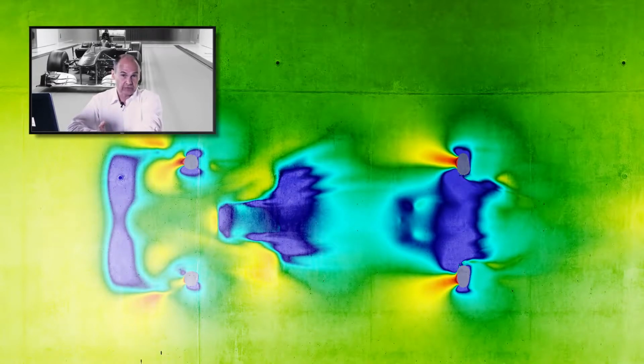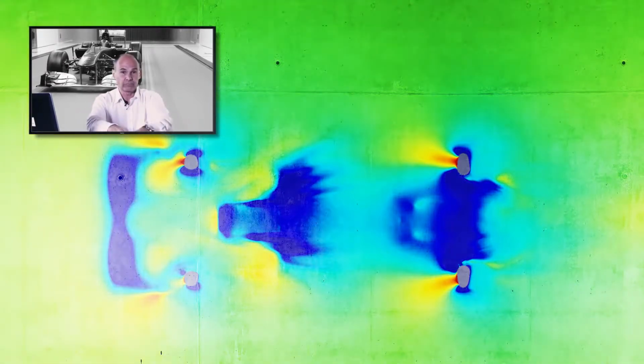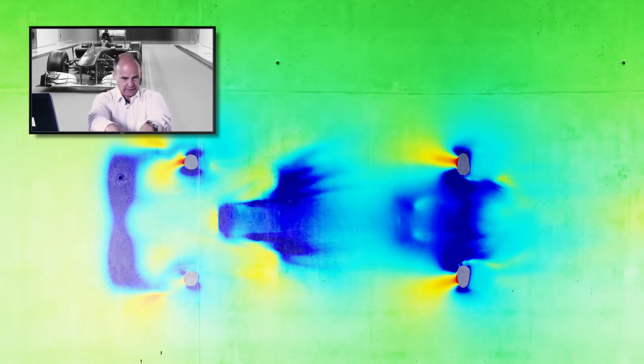So you apply the suction where the front wing is, and nowadays we just use CFD to tell us what the map is of pressure on the surface that we're running on. But in the past we would, through experimentation and logic and a bit of aerodynamic knowledge, work out, okay, most of it will be where the front wing is, then you'll have other suction where the diffuser is. And so we then would regulate boxes underneath the belt to control where the suction was.